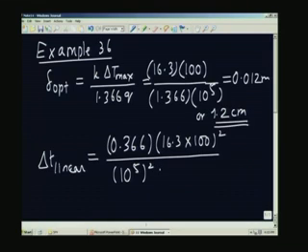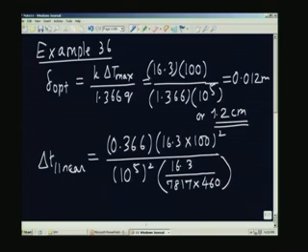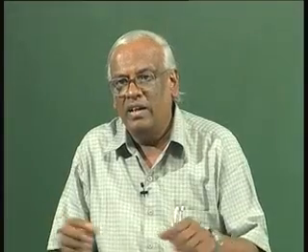I will write it like this: 16.3 divided by rho is 7817 multiplied by C is 460. These are the values which were earlier given on the board, and this will be in seconds, and this comes to about 21.5 seconds. So, the slug can operate for about a little more than 20 seconds without exceeding the 100 degrees temperature rise which is specified in the problem.